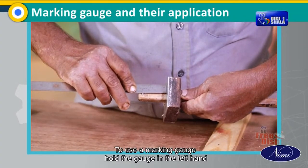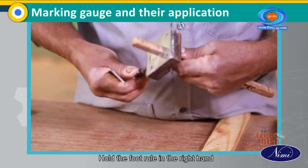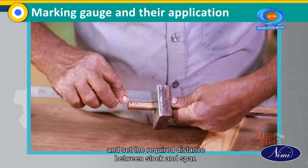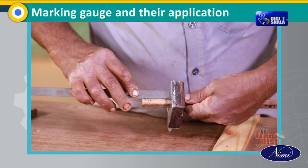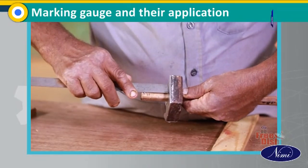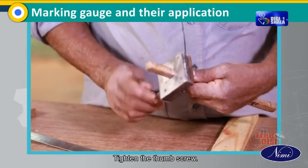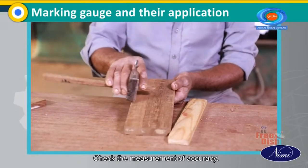To use a marking gauge, hold the gauge in the left hand keeping the spur up. Hold the foot rule in the right hand and set the required distance between stock and spur. Keep the graduation of foot rule in front. Adjust the stock with the help of your left hand thumb and index finger. Now the marking gauge is set. Tighten the thumb screw. Check the measurement for accuracy.